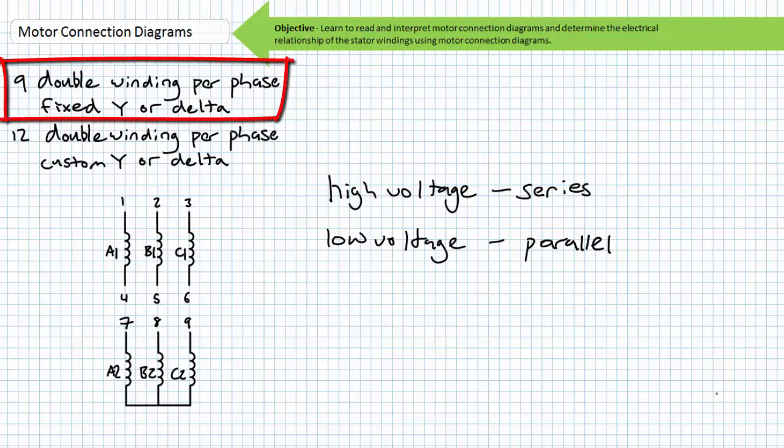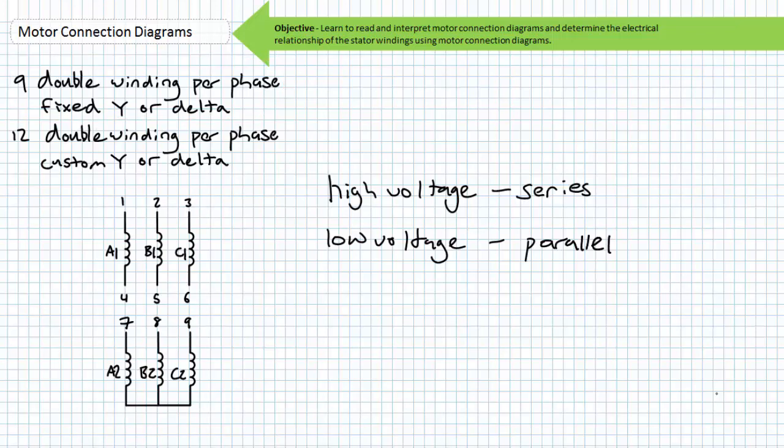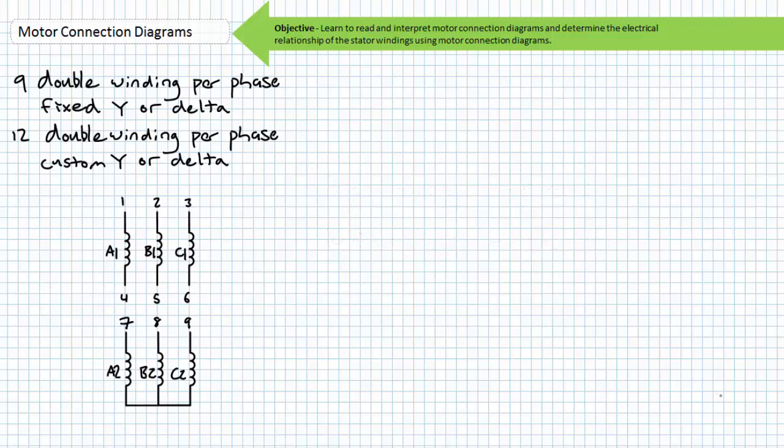9-lead motors are essentially an extension of 3-lead motors, in that a technician does not have a choice over Y or delta configurations. These motors typically feature windings pre-wired in a Y or a partial delta. The remaining leads can be wired in series or parallel with the pre-wired Y or partial deltas to allow connection to a high or low voltage source. Consider a 9-lead Y-configured motor.